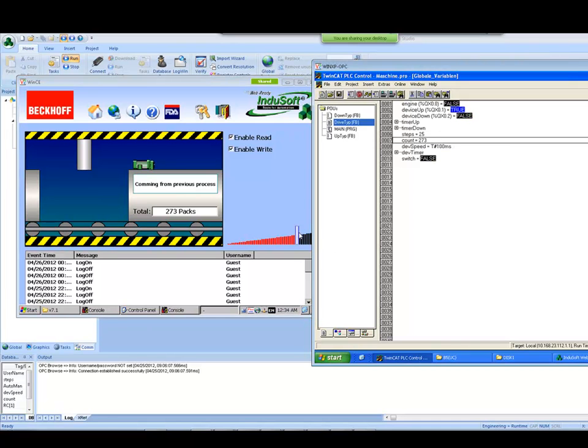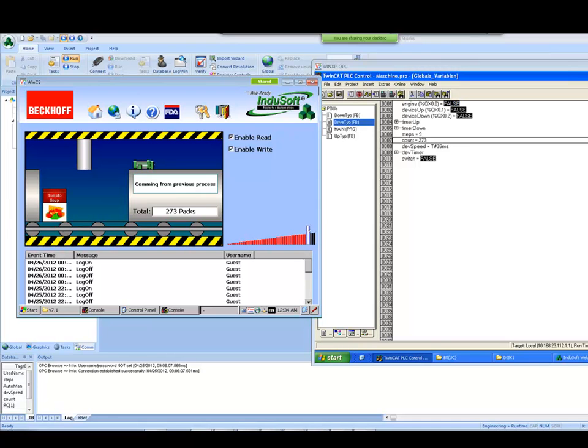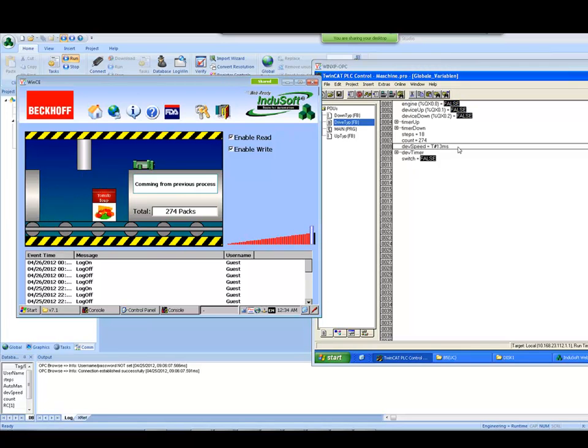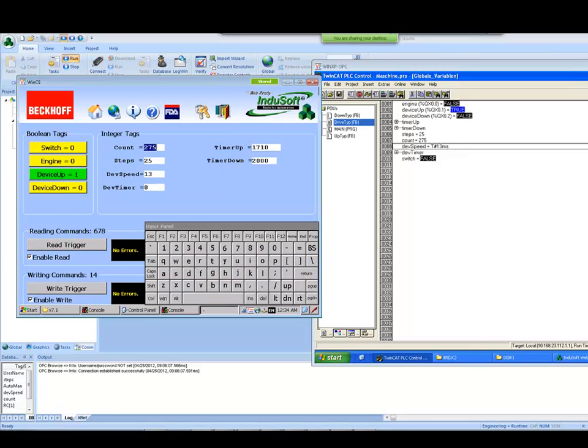I can write the values to the speed. So if I go here on the Windows CE screen and change the value, so I'm writing a new speed to the server. Okay, so I'm gonna go here, change and write. So I just wrote a new value to the server, the value 13, and the same thing that I was doing on my PC, I can do on the Windows CE as well. So I can write new values to the counter.